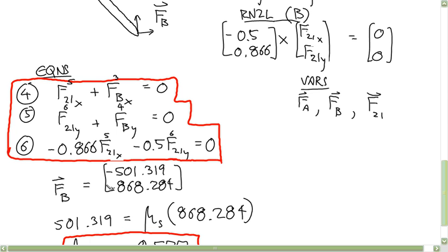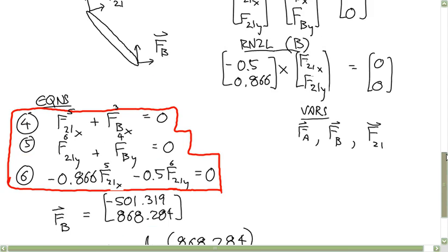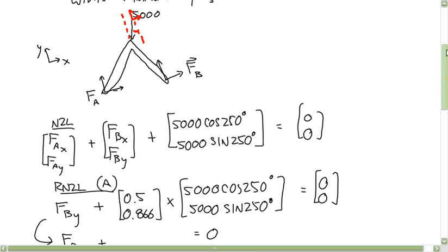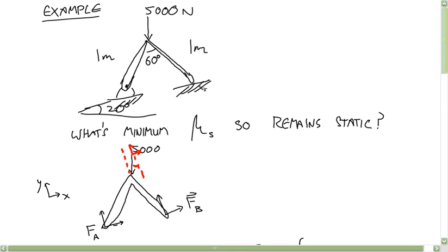And now since I already rotated the coordinate system, I don't have to do any dot product stuff to turn this force vector into a component of a normal and a component of friction. So we can just set the friction force equal to the coefficient times the normal force. If we'd used a standard coordinate system, then you'd have to break that up into a normal force that's perpendicular to the ground, and a friction force that's parallel.